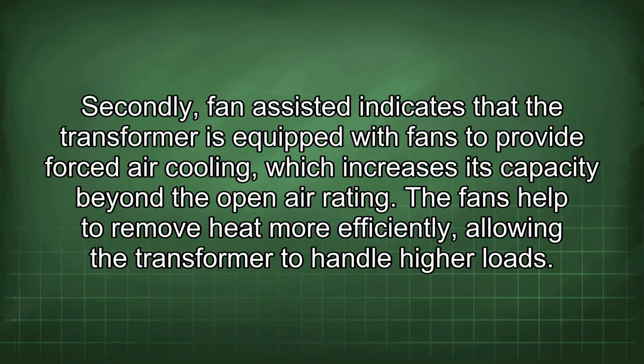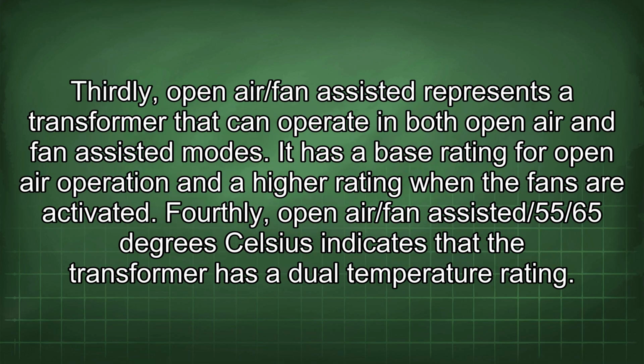Secondly, fan-assisted indicates that the transformer is equipped with fans to provide forced air cooling, which increases its capacity beyond the open-air rating. The fans help to remove heat more efficiently, allowing the transformer to handle higher loads. Thirdly, open-air/fan-assisted represents a transformer that can operate in both open-air and fan-assisted modes. It has a base rating for open-air operation and a higher rating when the fans are activated.